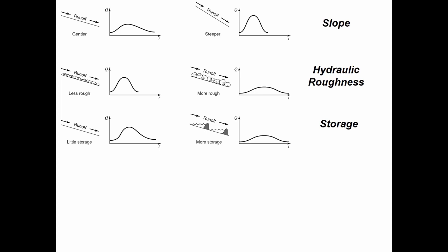But as a general trend, the more storage you have en route between the watershed and its destination, the delay and the reduced peak is what you'll observe. I know this is the idea of dams, but what's a smaller scale of this happening in real life? It would just be a channel that isn't going downhill at a uniform slope. So in a regular slope channel, and that's how most natural channels are. If you go up in the mountains, you'll notice they are just irregular in their downhill.